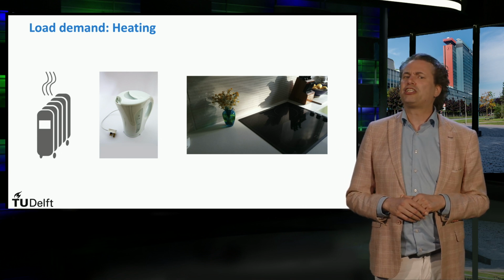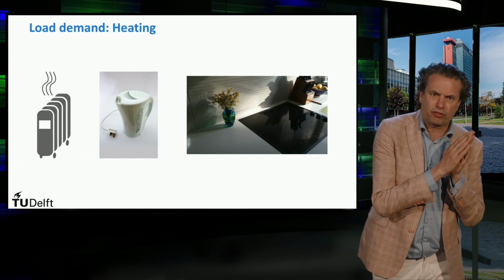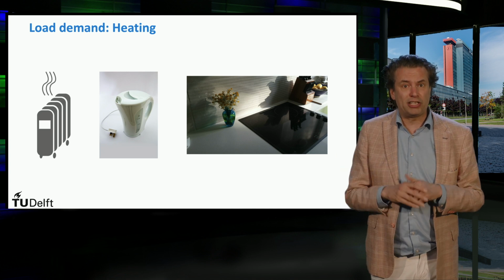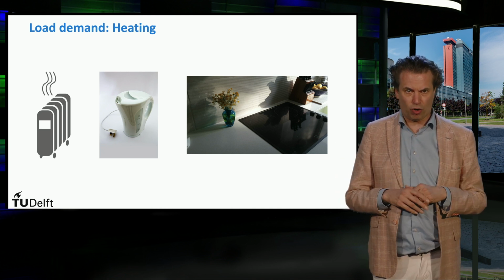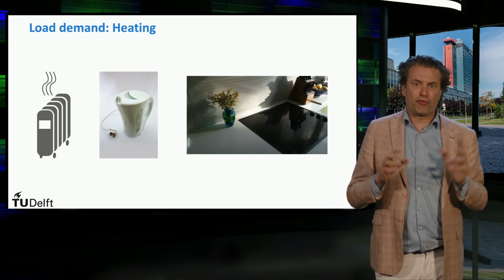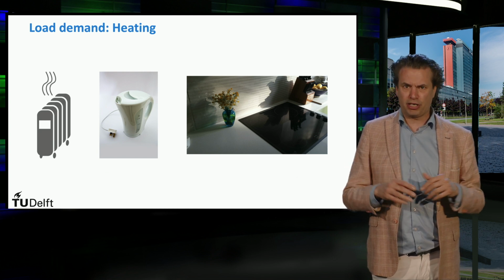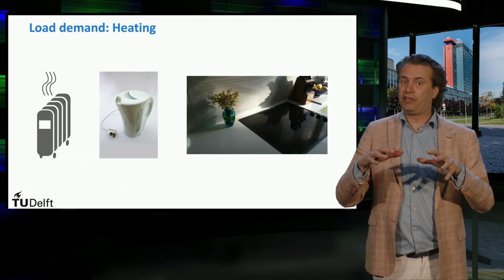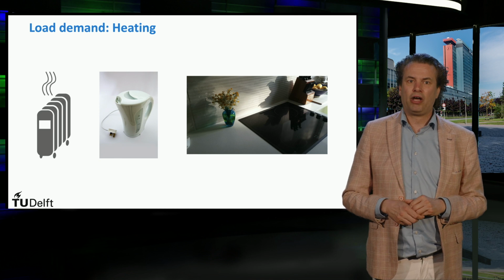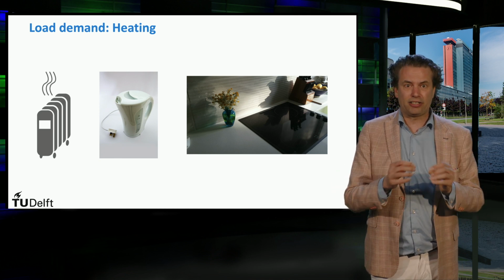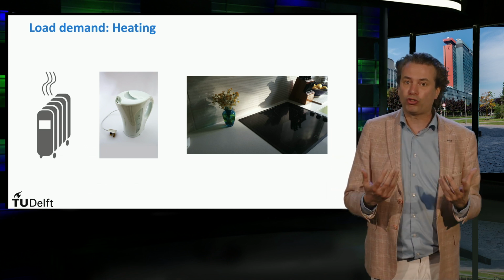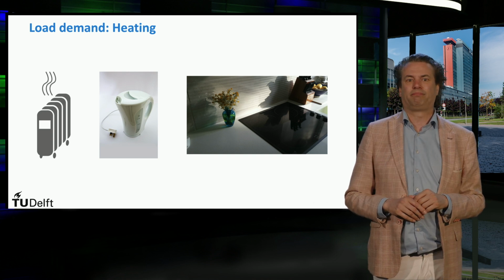A second approach is the induction cooker that transfers electrical energy by induction from a coil or wire into a metal pot based on ferromagnetic materials like steel or iron. The coil is mounted under the cooking surface and a high frequency 24 kHz alternating current is passed through it. The electromagnetic field induces large eddy currents in the pot that is close to the cooking surface. For high efficiencies, there should be as little electrical resistance in the coil and as much as possible in the pan so that most of the heat is developed in the pan.